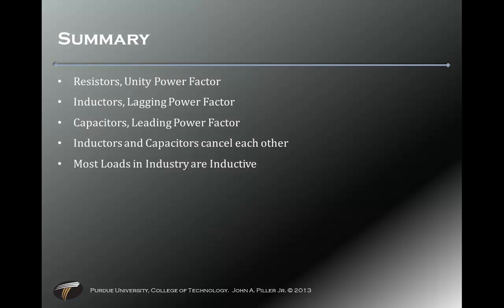Inductors are positive 90 and capacitors are negative 90. So when you add them together, you can cancel them out to increase your power factor to a point where it becomes 1, at unity. And most loads in industry are inductive. Thank you.